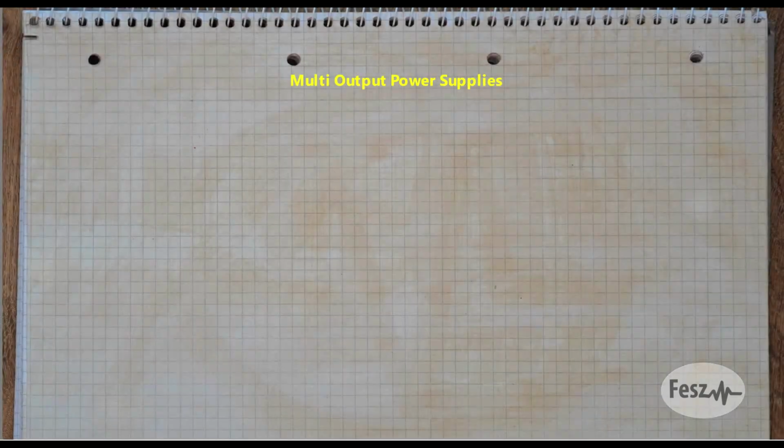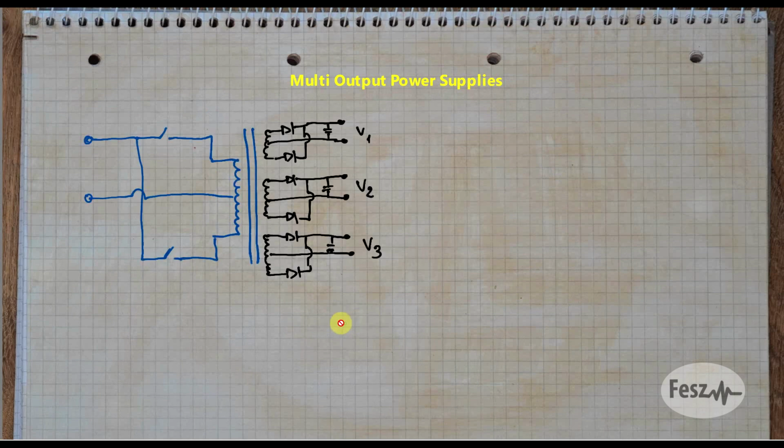Now, all of the previous categories had a single output voltage, but that does not have to be the case. So the next thing to observe is supply combinations that generate multiple output voltages. So one common example is something like a computer's power supply. A single push-pull driving stage that drives a transformer, which has multiple secondary windings for the various voltages that are needed in the system. Now, in general, with transformer-based topologies, multiple secondaries can be added for whatever voltage is needed.